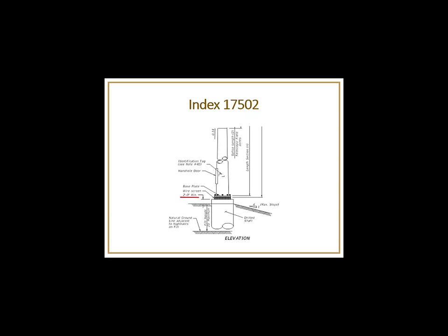Now, if that shaft gets moved in the field during construction, the EOR or somebody should go back and reevaluate what the top of shaft foundation elevation should be. And he should revise that elevation to ensure that it's 2 feet above the natural ground. So if you would, when you're setting foundation elevations, be sure to look at that and maintain that 2-foot requirement.